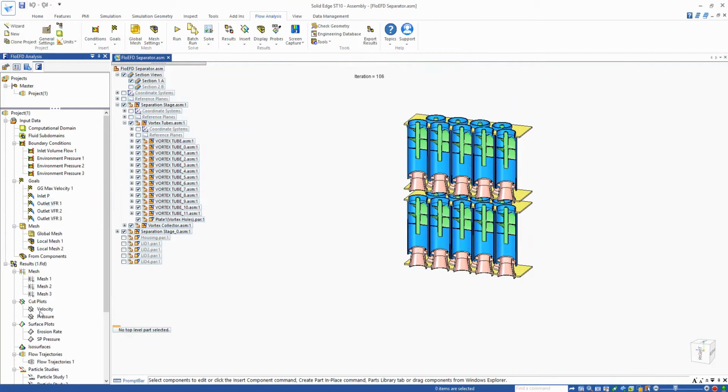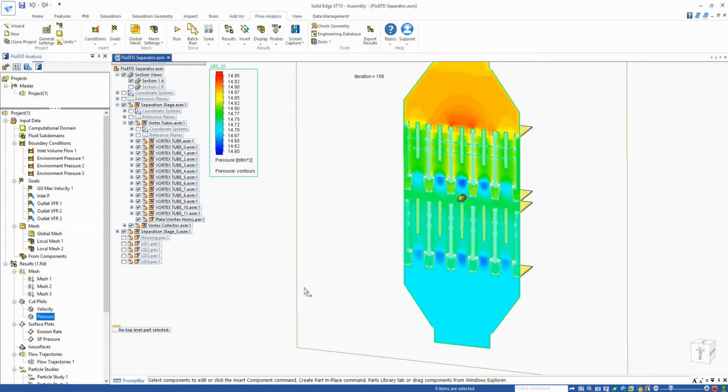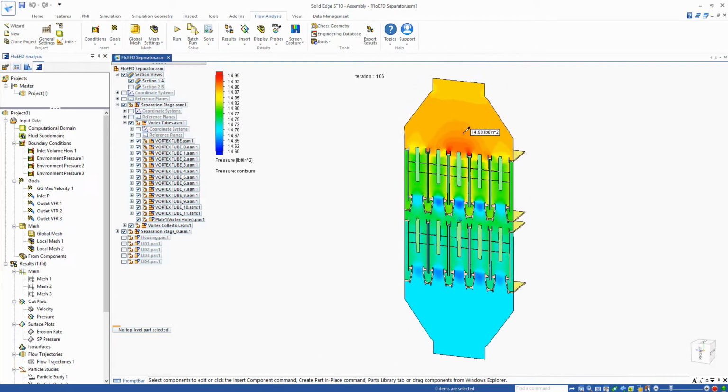We can also have a look at what the flow pressure looks like. So to maintain that 100 CFM, what's the delta P got to be? Well, we can see the inlet pressure and the outlet pressure, so maybe 0.18 psi or so upstream pressure is required to maintain that 100 CFM through the unit.